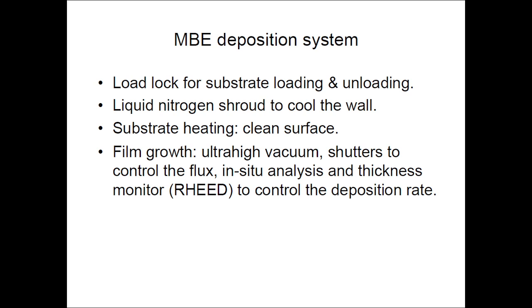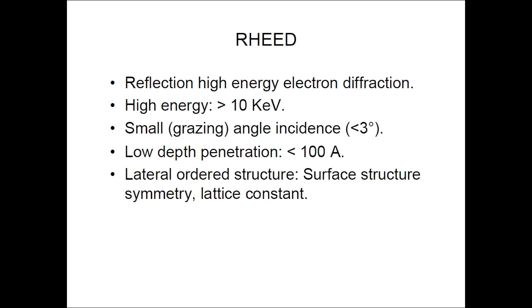And when you are doing the film growth at ultra high vacuum, the shutters will be controlling the flux, the in situ analysis, and the thickness monitoring by a RHEED to control the deposition rate will also enhance the quality of the thin films that you will be depositing through molecular beam epitaxy. So what is a RHEED? RHEED is reflection high energy electron diffraction.